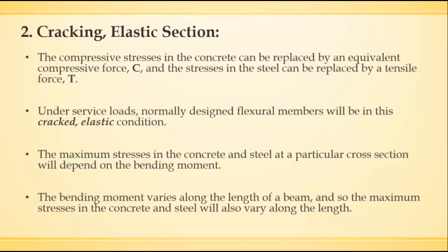In an actual structure, the bending moment varies along the length of the beam, and so the maximum stress in the concrete and steel will also vary along the length. As the bending moment increases above the cracking moment, the neutral axis remains at the same location, and the steel stress is less than fy.